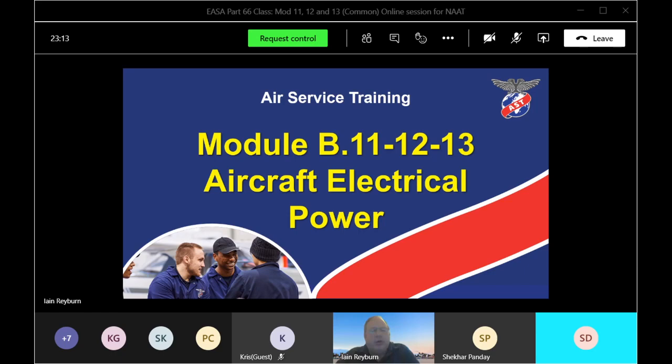Now look here again, if my output from a generator is high, in an analog system the excitation voltage would go down. But as I said earlier, this voltage in my solid state is constant. So if the output of my generator is too high, I'm now going to pulse the excitation field for a small time on and a large time off. Small time on and a large time off. So you can see the average excitation field has gone down, just like here. Therefore, my generator output has gone down.